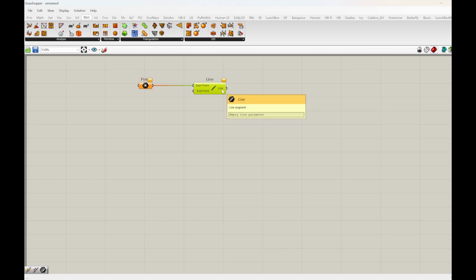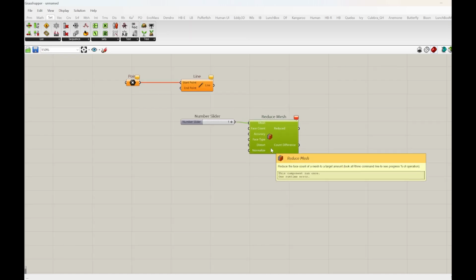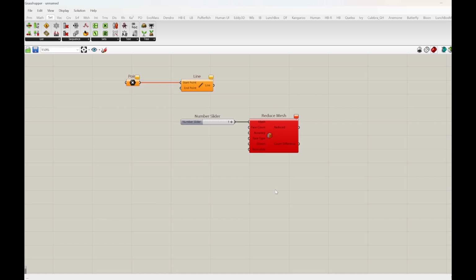There is also warnings that you will get. The first is a yellow warning. It's more of a warning, but it will still be cautious and move forward with it. There is also a warning that is a red warning, which means that it has to stop in place. As you can see in this example, the main issue with a red warning is because it does not know how to read the previous wire into the next wire function.